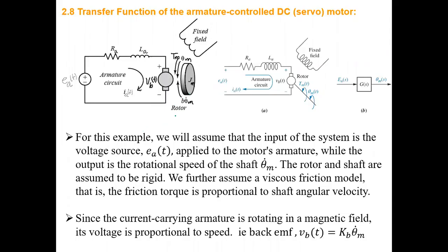So now, you have the input voltage here, right? This is the input voltage. So this current passes through this, and this guy rotates, right? Then what happens here? So then you see the back EMF here. Faraday's law of induction.